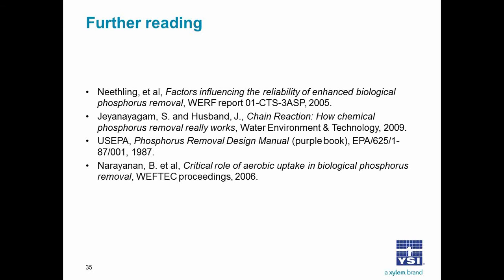We have one question coming in relating to the online analyzer. Does it monitor P, total P, or orthophosphate? Yeah, good question. So the analyzers that we have talked about today measure only orthophosphate, and that is the dissolved component.